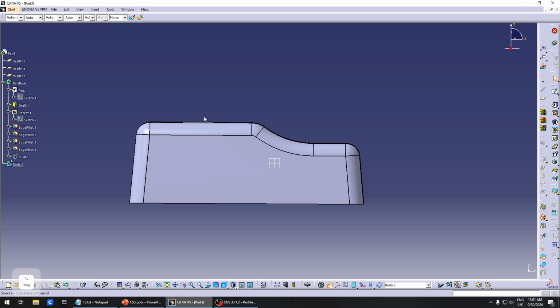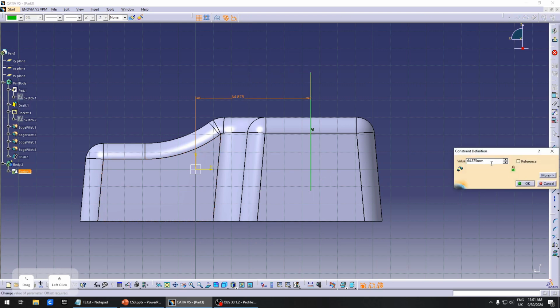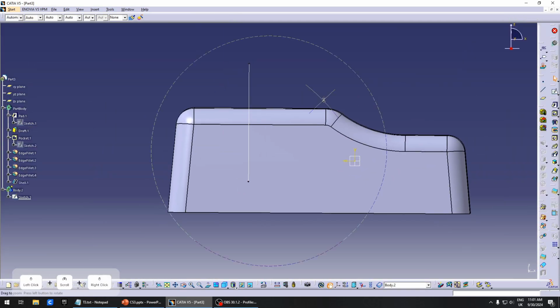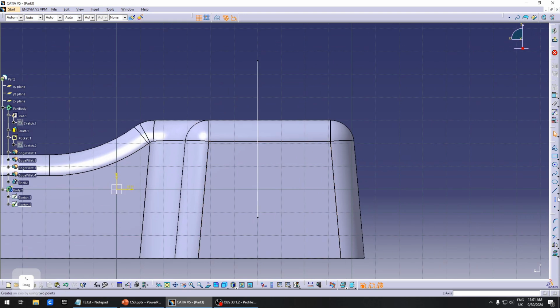We will translate that one over here as well. So to do that, we will create a sketch. At first, we need an axis for this, 60 millimeters away from this. Okay, good. Secondly, we need another sketch. And here we will draw our profile.